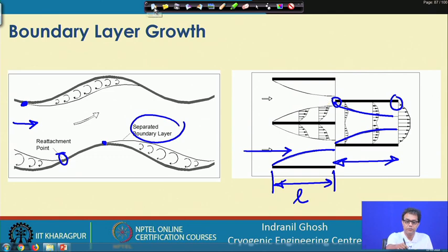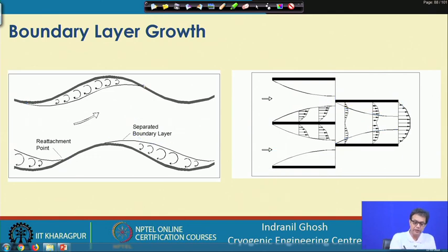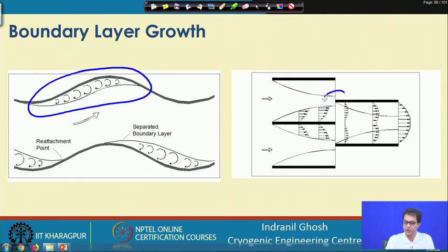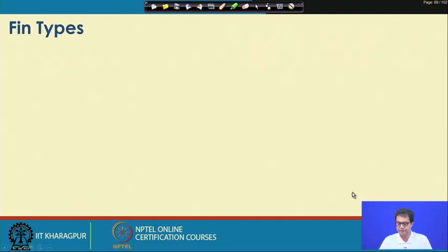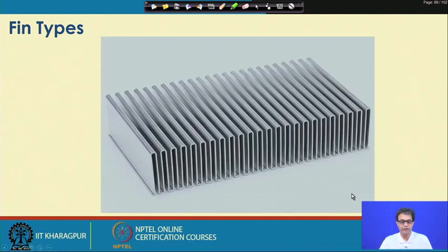Okay. So, in this one the pressure drop penalty is a bit less as compared to this side, but particularly when we go for very high heat transfer rates, we look for this offset strip fin, and this is in regular use in different kinds of plate fin type heat exchangers. So again, these are some of the pictorial views.